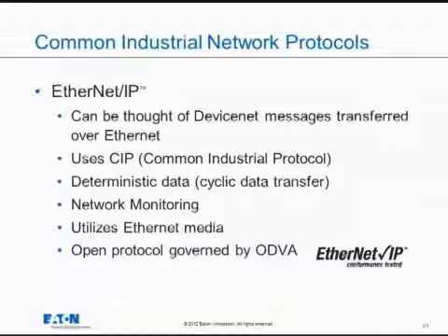Then the last one here is Ethernet IP. And it can be thought of as DeviceNet messages transferred over Ethernet. You know, we had Modbus and Modbus TCP. Now we've got DeviceNet, we've got Ethernet IP. That's kind of the quick and easy way to explain it. It's not entirely 100% that way. But it also uses the Common Industrial Protocol.